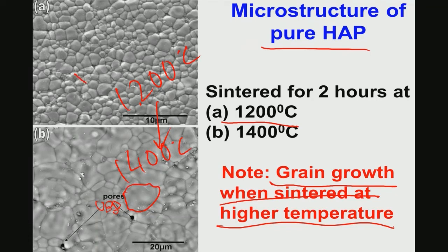For mechanical properties, the typical microstructure required is a uniform grain size distribution, not a bimodal type of distribution, and also a finer grain size. In material science, it is well known that the finer the grain size, the better the mechanical properties. Better mechanical properties meaning hardness and strength properties. Okay? Fracture toughness depends on various other parameters, depending on what kind of material you are considering.